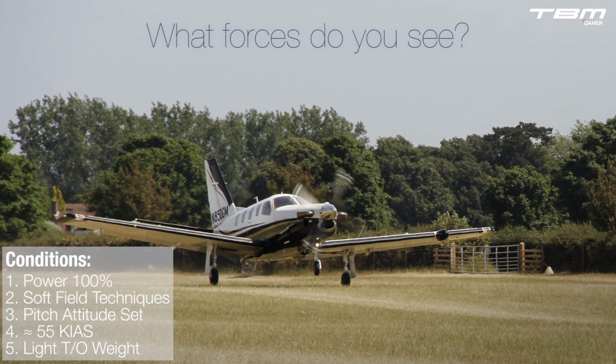This image of a TBM 850 was taken during the initial stages of the takeoff run. Power is at 100% torque. Soft field takeoff technique is being applied. For the purposes of this review, the pitch attitude is set. Indicated airspeed is accelerating through 55 knots. The aircraft is light on fuel. Payload is at a minimum, and only the pilot is on board.